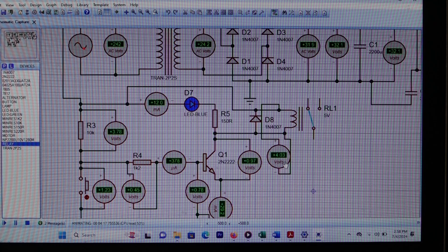Patricia? It's less than 5 volt. So according to the theory, the minimum or typical trigger voltage required to trigger the 5 volt relay switch is 5 volt. But in these simulations, we see that 4.03 succeeded in triggering the relay switch. So these are the drawbacks or challenges of the simulation software. But we'll do the same measurements in hardware to verify. Okay? Take a note, my dear students.